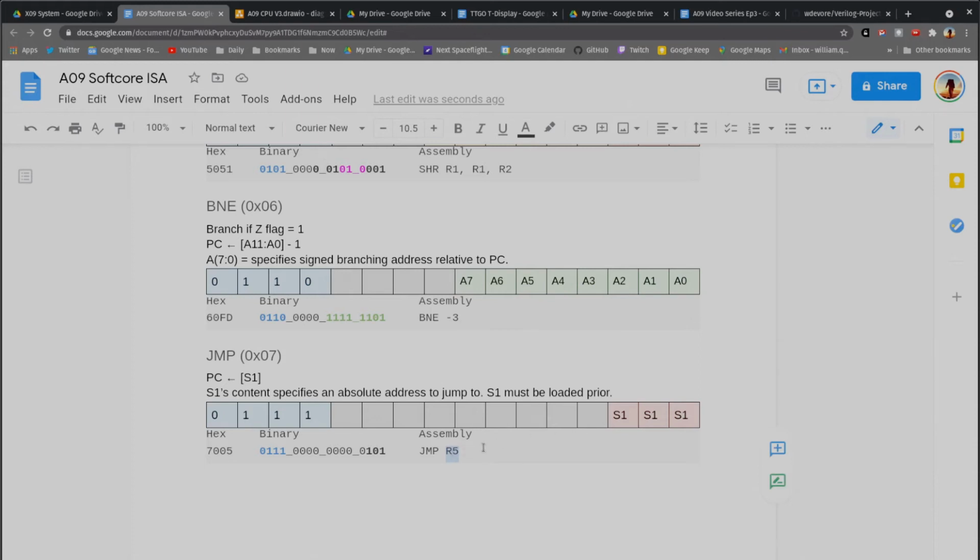You can jump all over the memory using the jump instruction, but in this case you can only load it with 8 bits based on our load instruction, so you technically can only jump forward 256 bytes, but you can't jump backwards. Again, we're just keeping the processor simple.